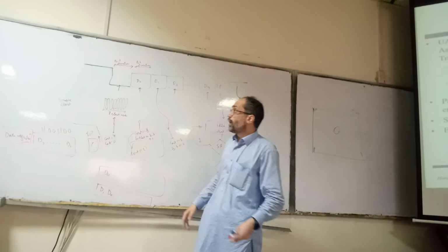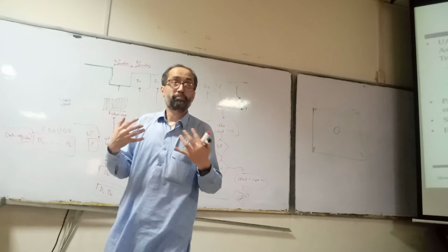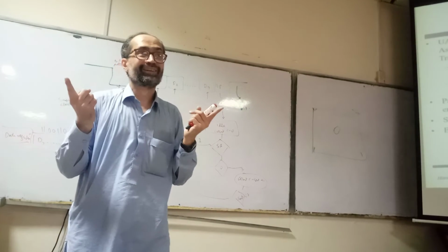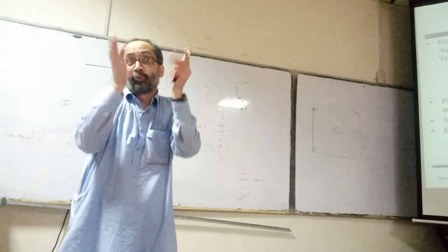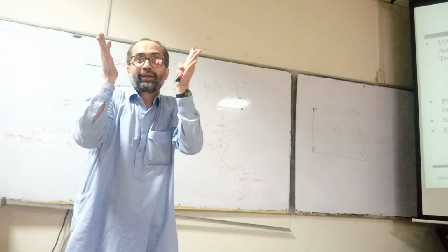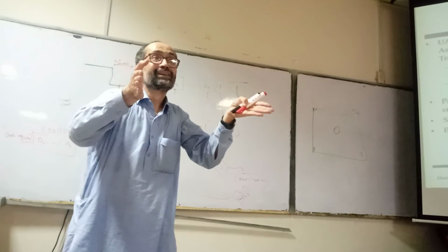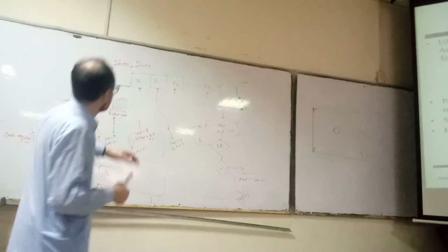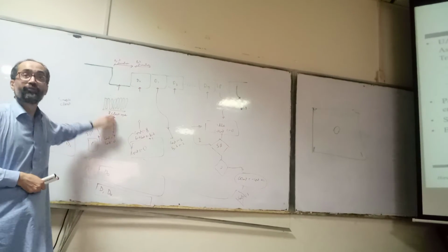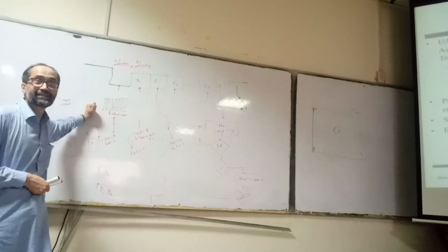So all these parameters are set by the baud rate. Now if we have one sampling frequency and if we change the baud rate, the number of clock cycles will also vary, if the clock frequency is the same.